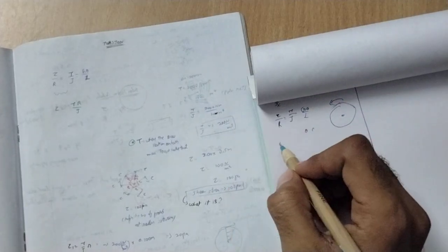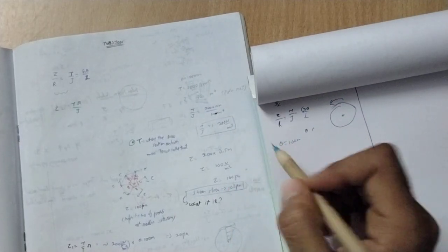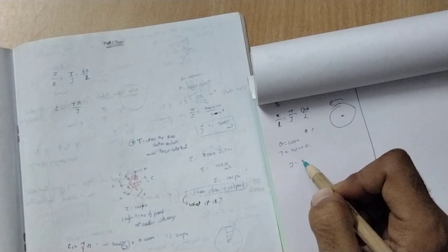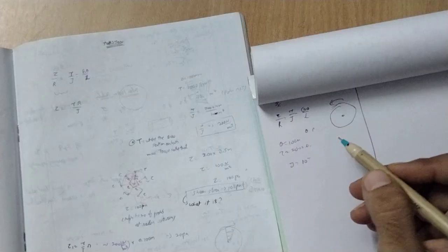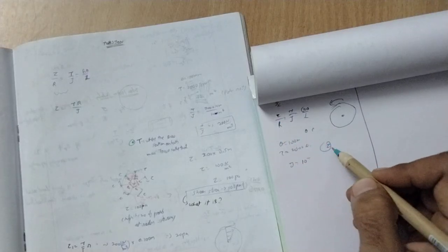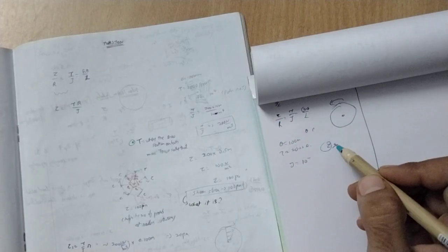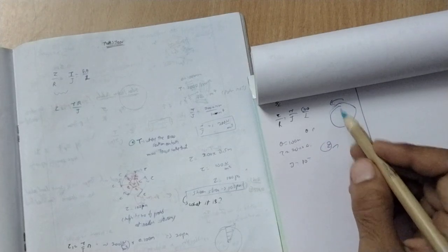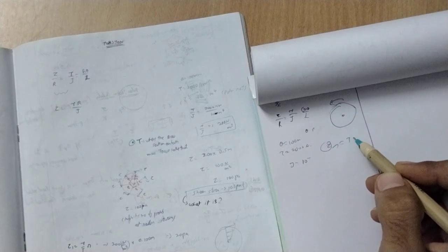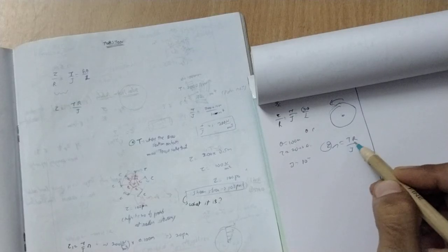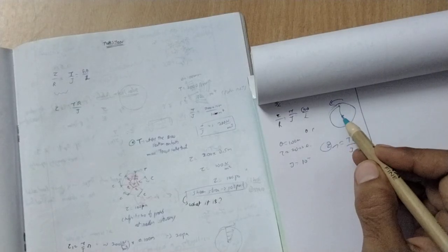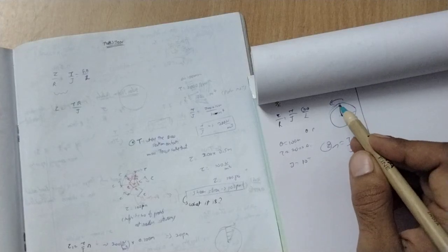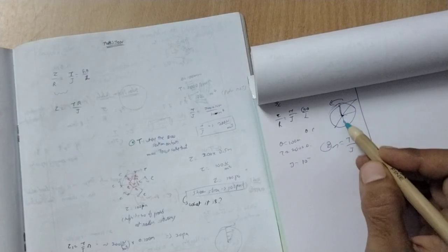You can see diameter equals 100 millimeter and the torque given is 2000 Newton meter. J is the polar moment of inertia, 7.4. So we can easily calculate the shear stress by putting the values here. What is the shear stress applied at each location? It is tau equals T into radius divided by J. You can see the radius on this side is this one. If you put r equal to 0, the entire shear stress will be 0.